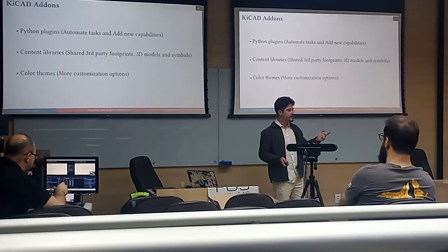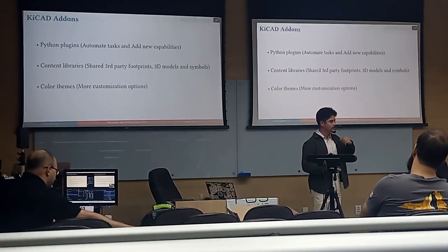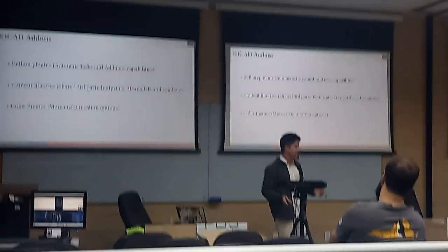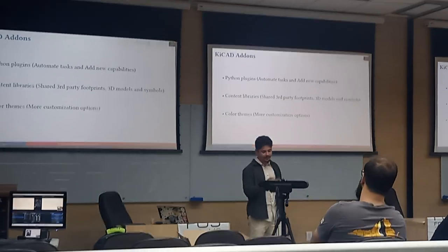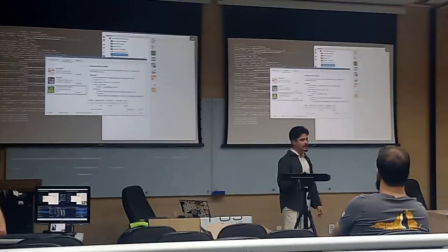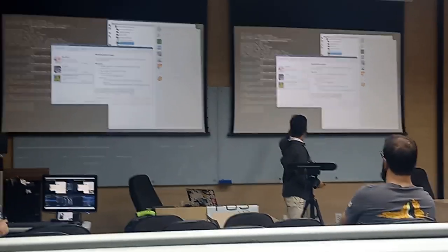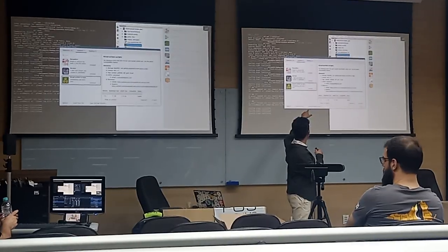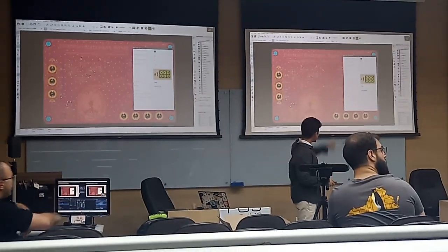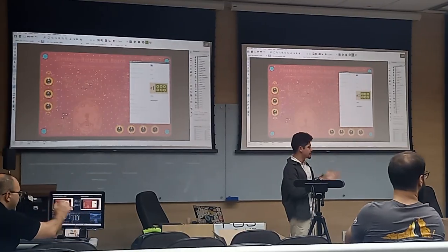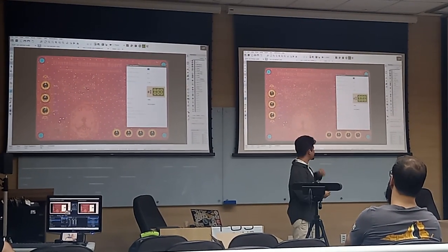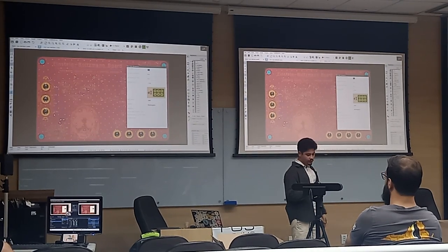And for example, you can share your 3D models, your symbols, all of this, and also share your color schemes. Why not put a Dracula scheme on KiCad? You actually can. So okay, you go to the store. This was the old store. I think KiCad 8 has a much nicer store, but you choose your plugin. This is my installed plugins. The repository has 81 plugins. You choose this one, the KiCad action script. And with this, just specify the parameters of your via stitching, the distance between them, the clearance, all the things, the pattern that you want, and it's done.